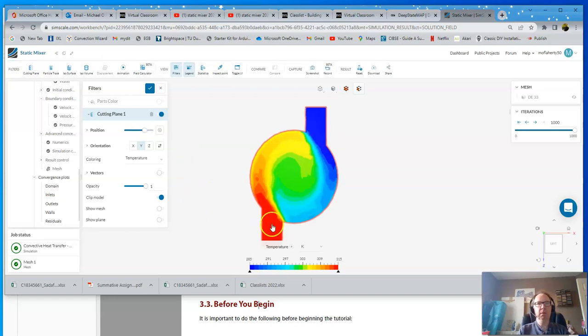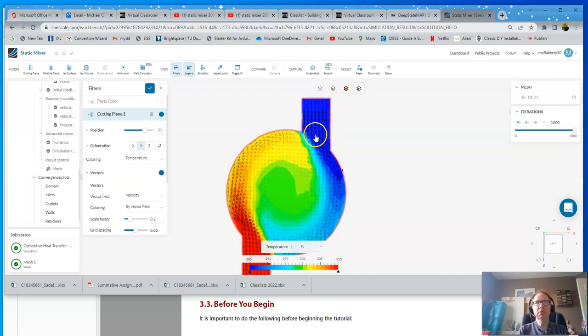I want to check what's happening with the velocity as well. You see on this menu over on the left here, the vectors. You can turn on vectors, where it represents the velocity by little arrows. And I'm going to zoom in on this. You can see the arrows at the inlet there. You have uniform velocity, and that should be 2 meters per second coming in there, and in here, and then they spin around each other and they mix up around here. And so you get a rotational flow, so zero rotation in the middle, so getting very little velocity in the middle.